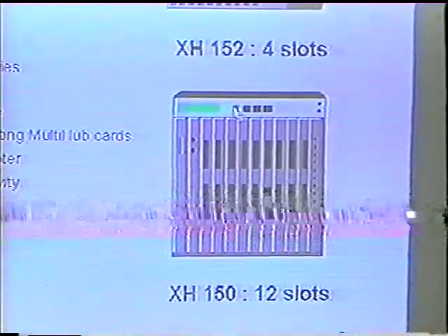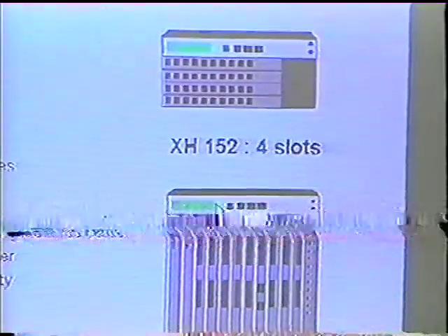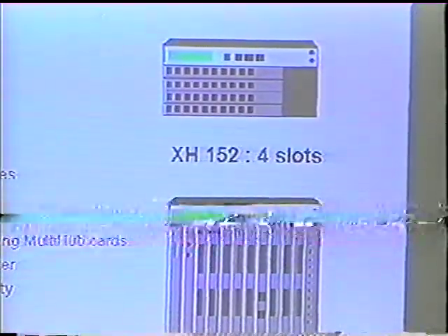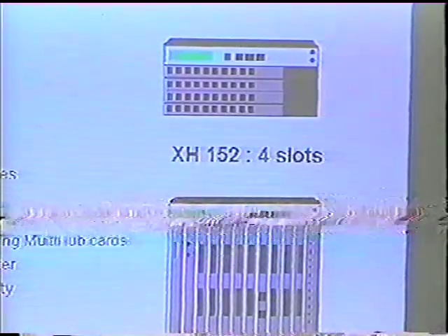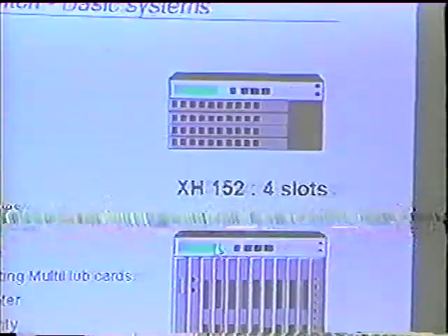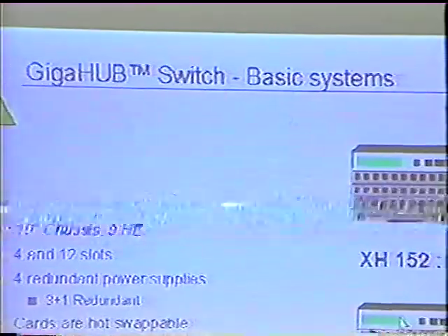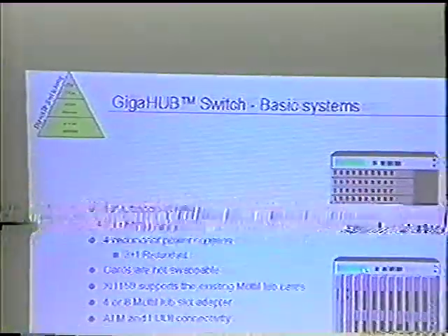These two systems have LCD and push key buttons above. You can see it here. So the user can locally put commands or look at monitoring indication through this LCD. You can give basic commands like attach or detach port, select ports to be 10 or 100 base, full or half duplex.